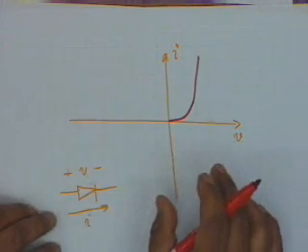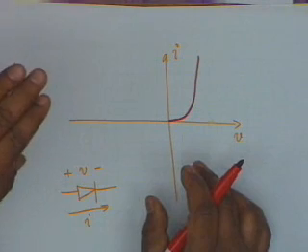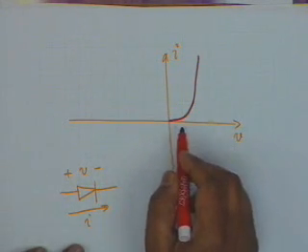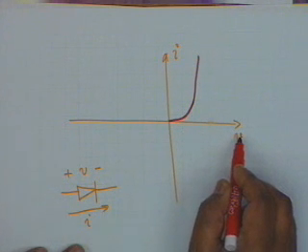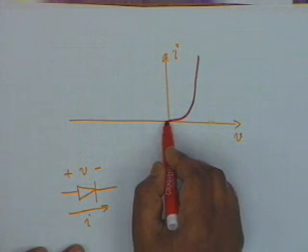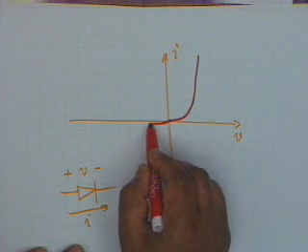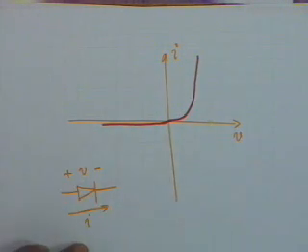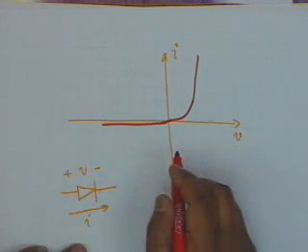As the forward bias is increased, the potential barrier is decreased further and further, and so the current rises. In the reverse direction, however, that is when the diode is reverse biased, there is a small component of current flows which remains almost constant, because the current flow is due to drift of minority carriers, but then there is